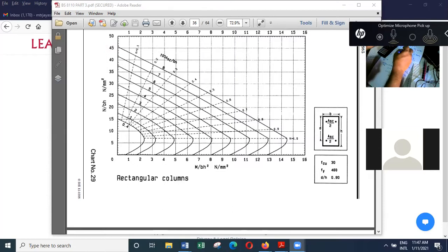So because of that reason, and also because in the shear wall the axial load also dominates, you'll find unless the moments are very large, this reinforcement cannot be reduced. But in certain situations, if the variation is high, then by using this method, every 1 meter, you can have a different reinforcement.